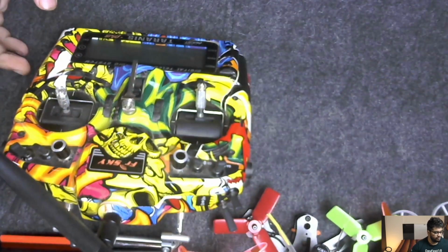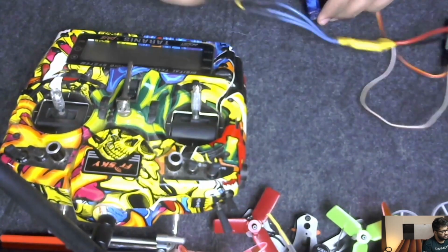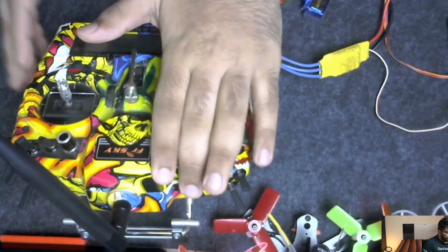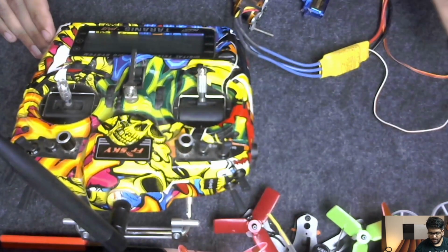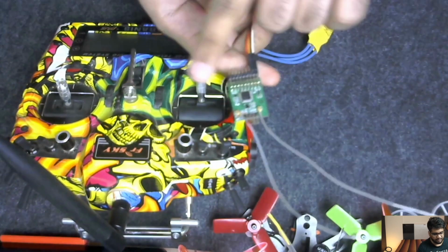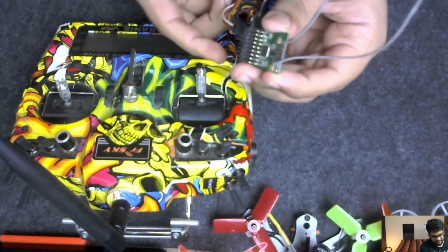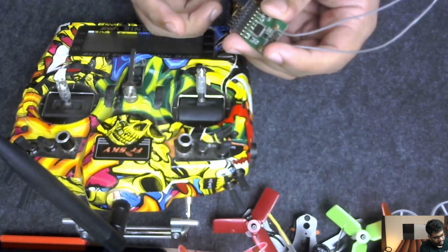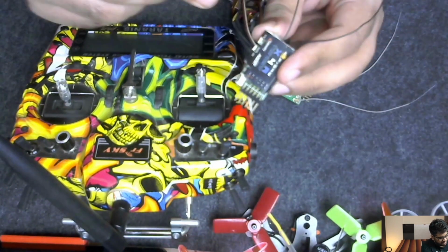So I have done a small setup here. This is my transmitter, and I have one receiver here which is connected to two motors, one servo motor and one brushless DC motor. So how does my transmitter know that it needs to talk to this receiver? We need to do something called binding of the receiver. I need to bind my receiver to my transmitter, and every receiver has a different process to bind it. In this particular one, I don't remember, but there is one button, or you need to short some pins and connect to the battery. For example, in this receiver, there is one button here.